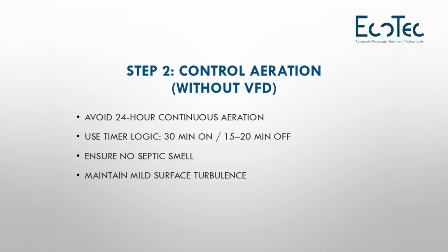DO naturally is higher. Operators see high DO and assume the system is safe. But high dissolved oxygen does not mean anything at all. It does not mean the biology is healthy. It means there is over-aeration. It may even mean that the sludge is aging.